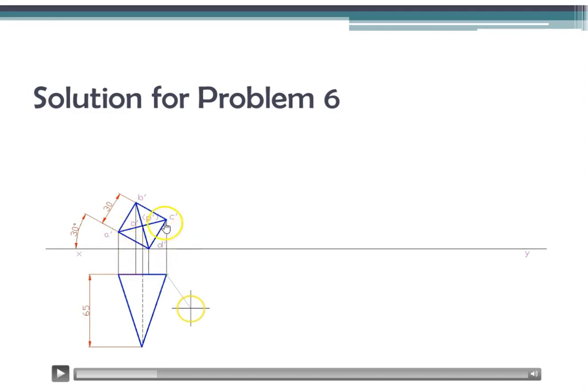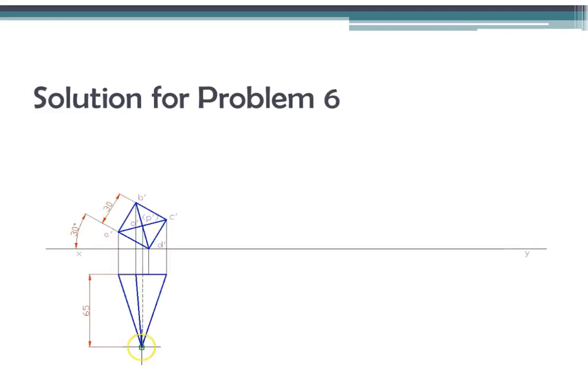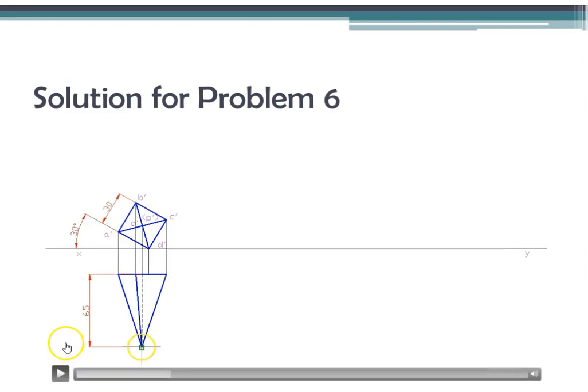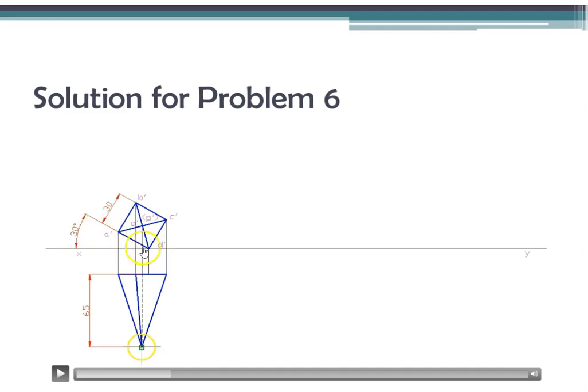When we showed the actual 3D, we might have made this side 30 degrees in the 3D view, but that is fine. The point is clear: the edge containing that corner, any of these edges could be taken and tilted at 30 degrees. Now let's see the next stage. The next stage is simply straightforward. This axis is inclined simply to the XY line, or to the VP.